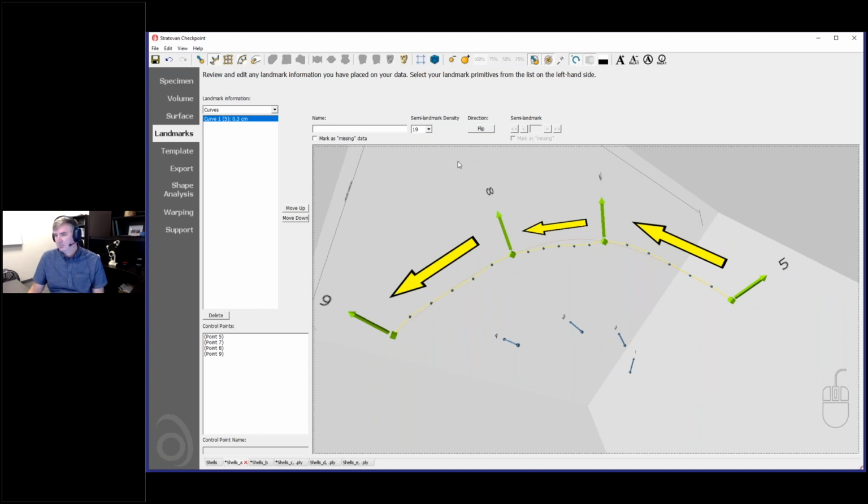David, in regards to this, is there a way to flip the direction of the curve and actually change the ordering? Yeah, you guys can do that too. So it's this, yeah. So I have this one selected, and then you do this. So the reason you do that is it changes the order of the sequence of points when you're exporting.